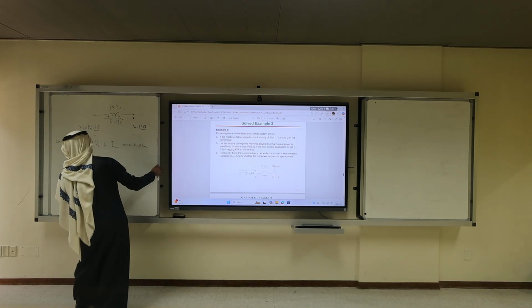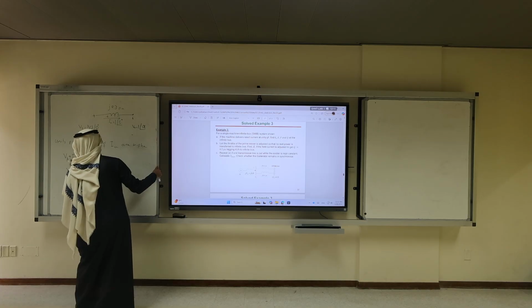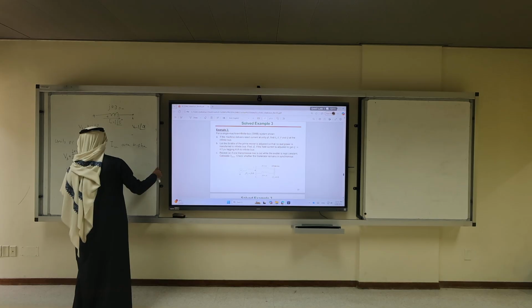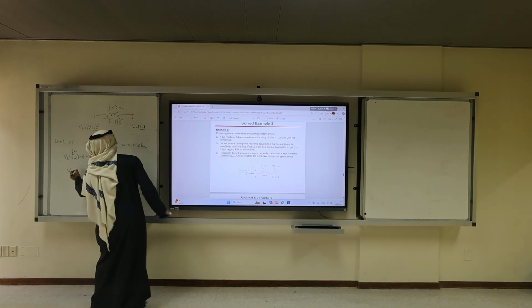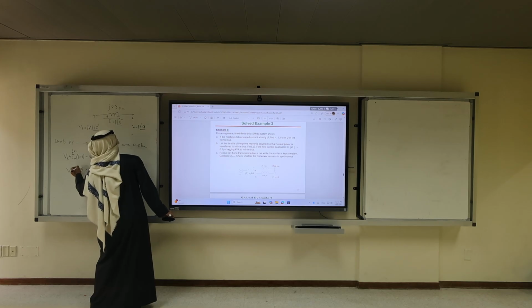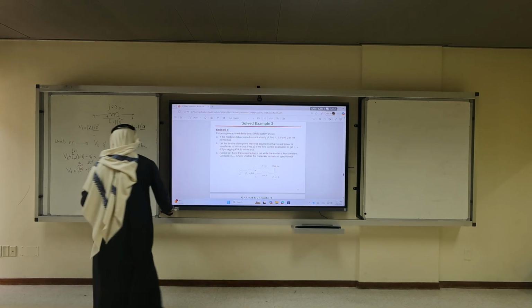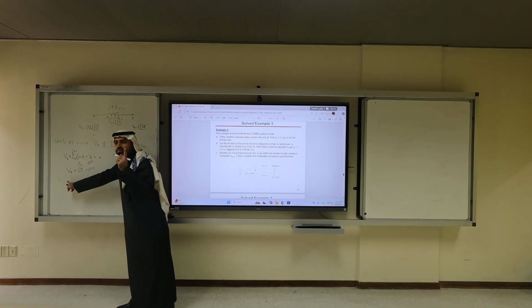So, VT is what? VB plus j0.3 times IA, which is 1 per unit. Correct? And VB is what? VB is 1 at an angle of alpha. So this is VB, this is j0.3 IA. Get it? So here is the trick. You have two unknowns, one equation.